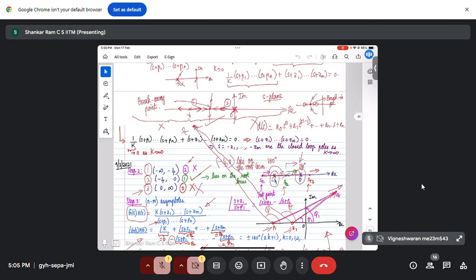Similarly, if we look at this particular figure, in this example we don't have that, but if we had, let's say, two open loop zeros on the real axis and two branches terminating at them, very likely that two branches may come from the complex plane, intersect at a point, and then break into the real axis. Okay, so those are what are called breakaway and break-in points.